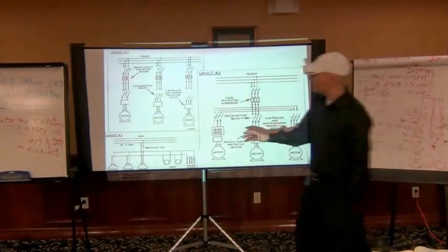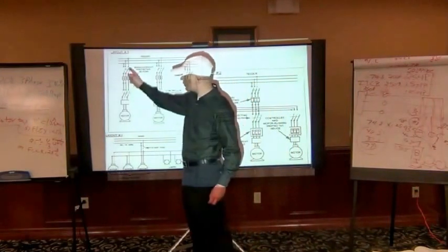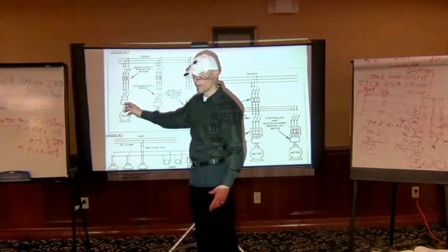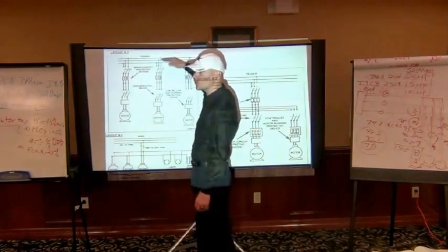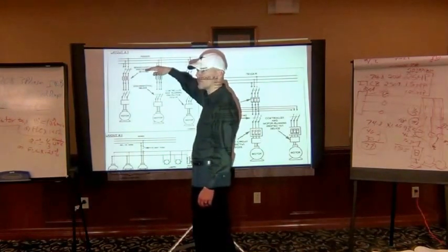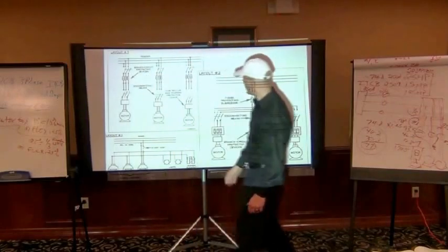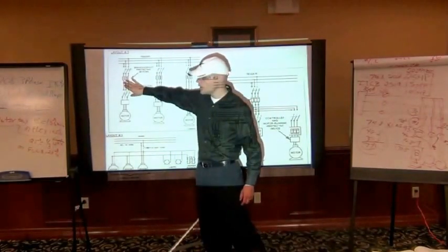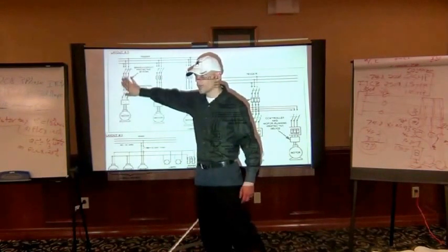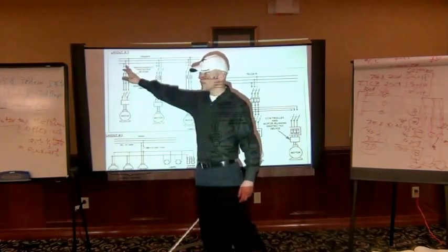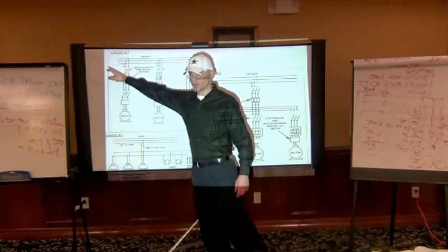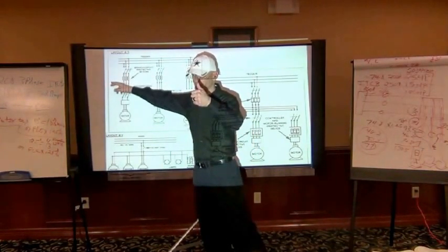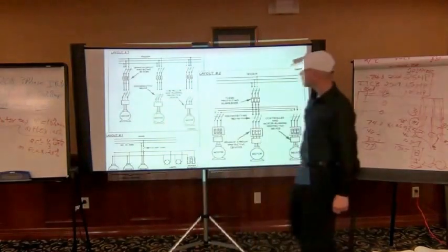But when we were talking about every time you have a single set of wires that go to a single motor, that's always going to be 125%, right? This up here would be the 125% of the biggest motor plus the sum of all others, okay? And then this set of protective devices on table 52 would always be sized just on that motor by itself. But the one up here for the feeder would be the one where we take the 250% of the largest motor, round up, add the FLA of the other motors, and then round down.